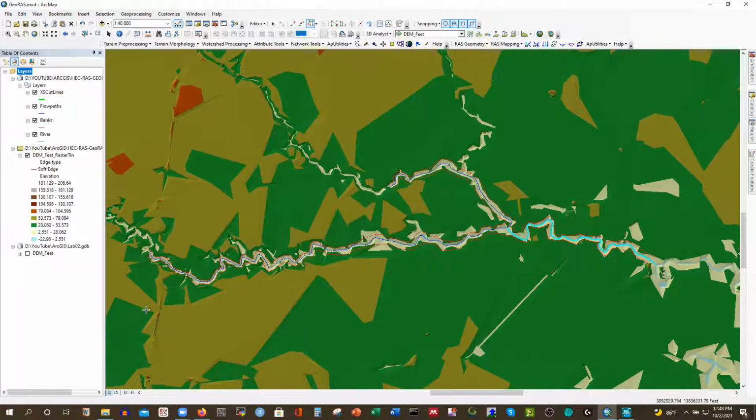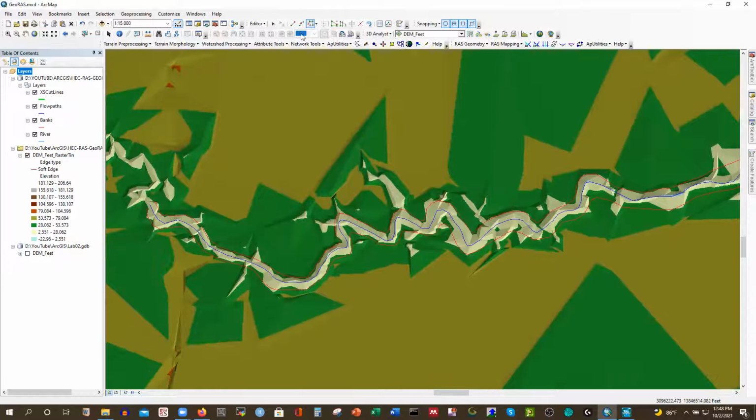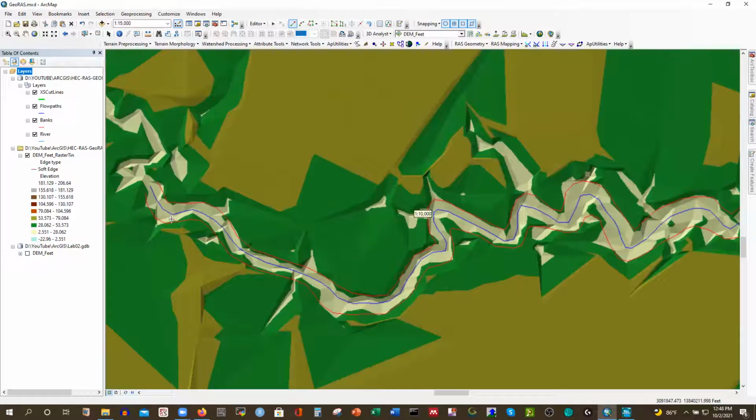Then, because this is flow path, we have to do the same thing for, so I'm gonna turn it off, and then straight segment, I'm turning that on. And here it is. Just follow this previous rule I mentioned for the left bank and right bank, this is the flow path. That should be pretty close to our bank line, so that our automatic cross section will follow this line, because that will consider this line pretty close to our bank. Even what you can do, you can even superimpose your flow path line over your left or right bank, but that is not customary. People